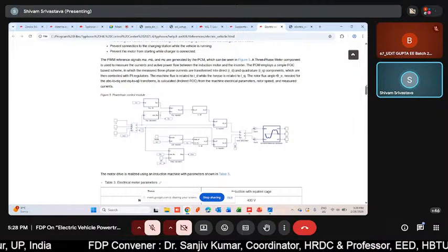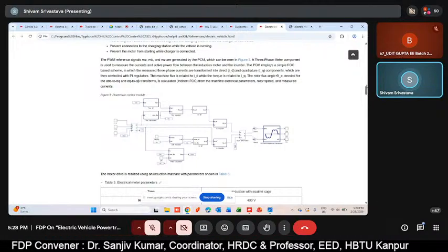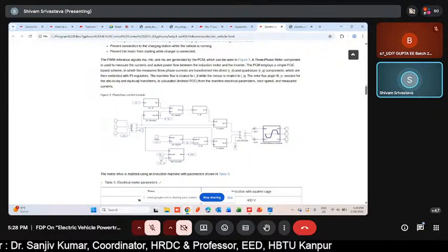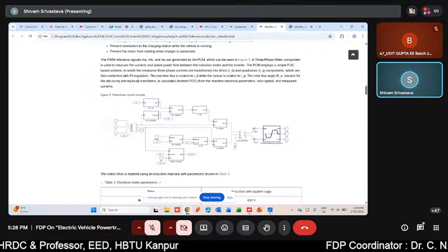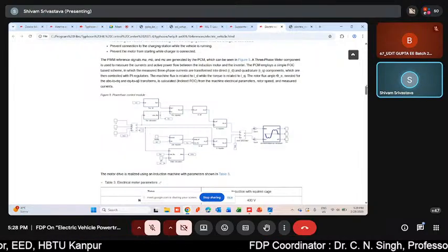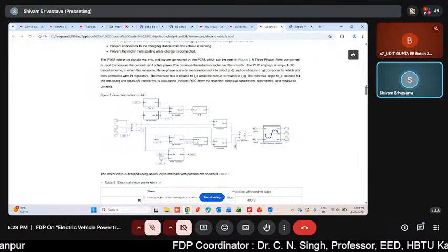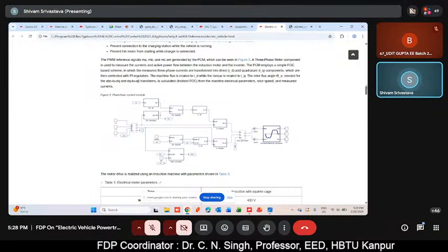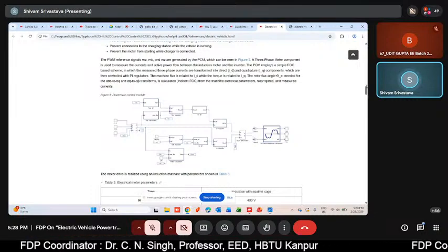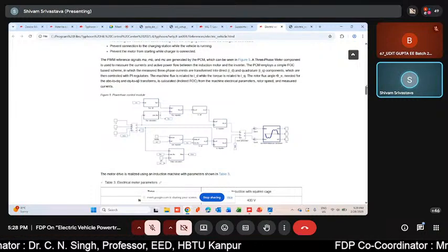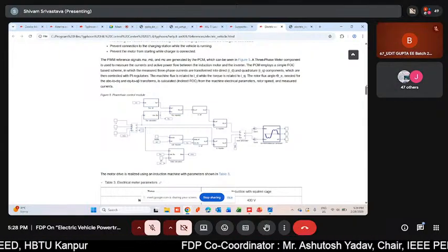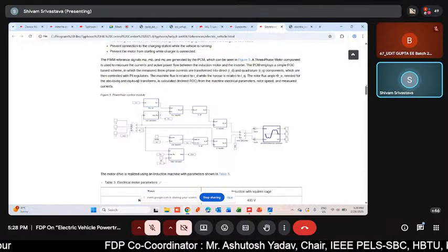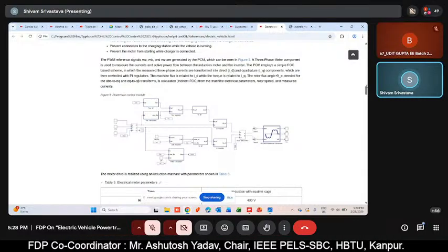Then we are focusing on the id current, iq current, and their reference speed, and on the basis of that we have an SVPWM reference generator where we are generating various PWM signals for the different legs of the inverter, by the name of MA, MB, and